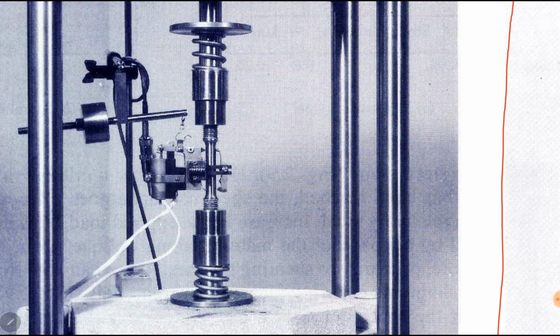If this force is parallel to the cross-sectional area, it means there exists shear stress in the necking region. So mostly ductile materials fail due to shear stress at the end in the necking region. Even though the external force is tensile in nature, a normal stress, in the necking region the material suffers from shear failure.